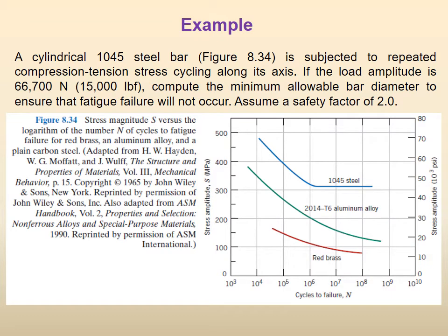So we were just telling you that the material that we have here has an endurance limit, so that question is done. But now it is a stress and number of cycles to failure. If you have noticed, the brilliant thing is that in this graph, a stress amplitude is directly given rather than the stress. So when I asked you whether we should use the stress amplitude formula, because normally it is load upon area, here the load amplitude is directly given.